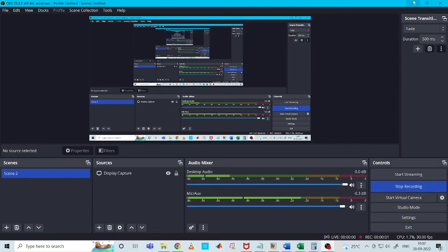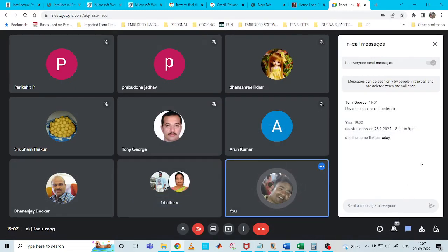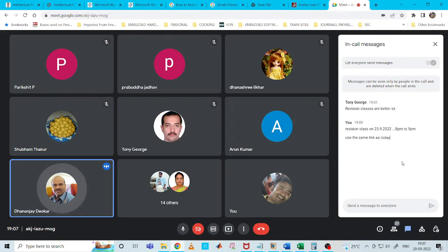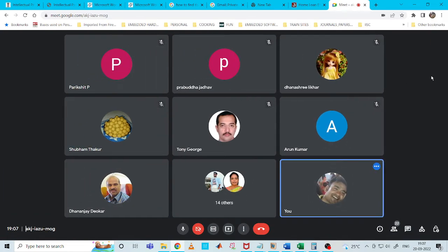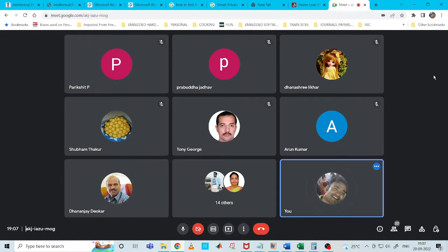PC will be having the address of the next fetch cycle. So we can say in a different way that PC will be holding the address of the next instruction. That's all, holding the next instruction. It will be coming after 8 bytes, correct, not after 12 bytes.